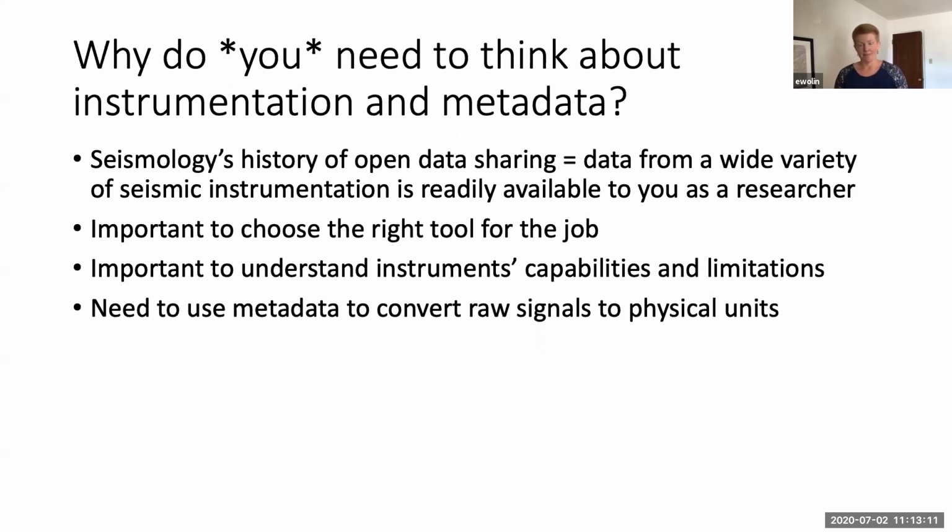That's a great thing because you have access to all of this data, but you also need to be aware of how that data is acquired and if you're using the right tools for the job or not. So you need to understand the instrumentation that recorded that data and what it can and can't do for you. You also need to be able to look at metadata and use it correctly to convert those raw digital signals to physical units.